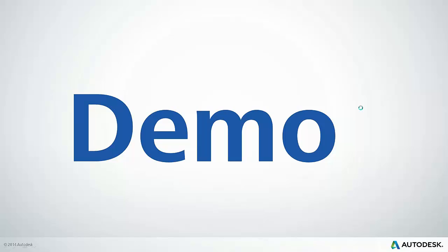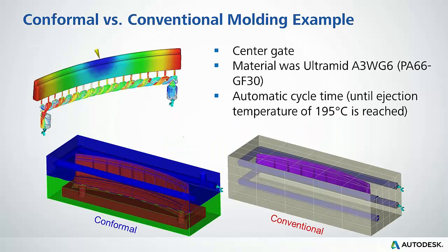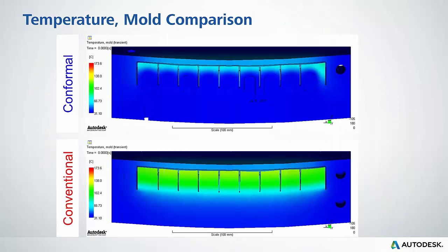Okay, so as a comparison between conformal cooling and conventional, it's consistently better with the conformal approach, and it just makes sense where if you get creative with where you're putting water, it's going to cost more as far as construction methods, but you're going to achieve a more uniform temperature in a faster cycle.